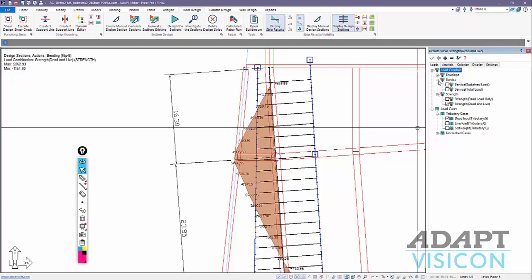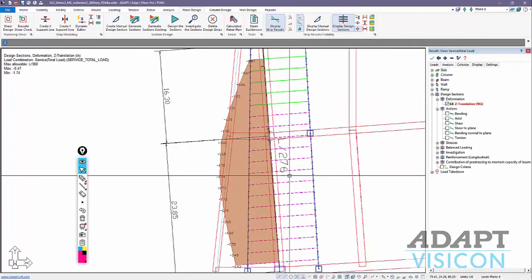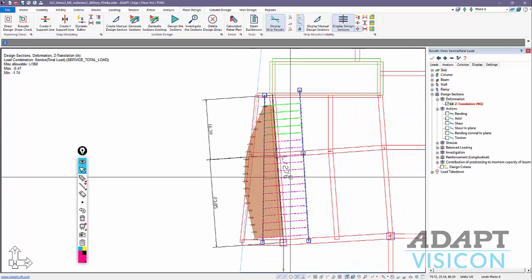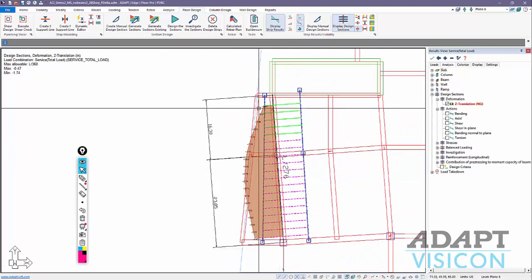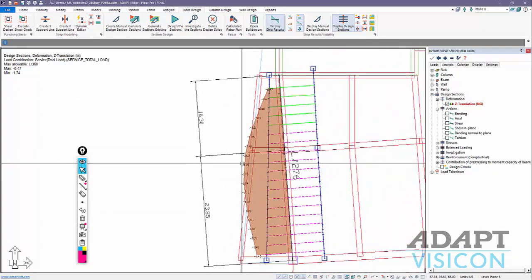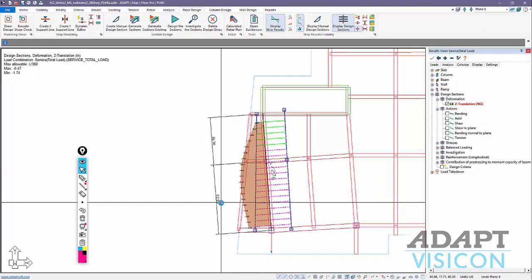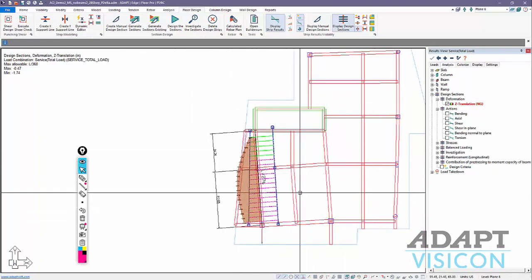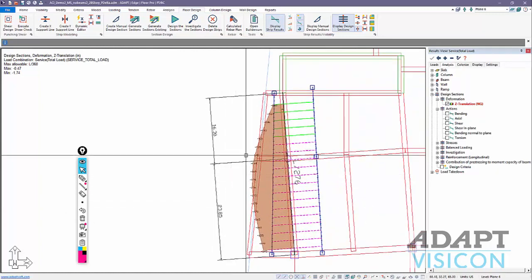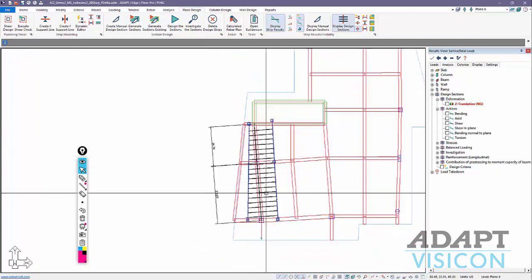If we go to a service combination, service total, we might want to check the deflection along the beam. So the deflection is L over 276 for this full span, and these are just integrated deflection values over the design cuts. These are not long-term nor cracked deflections. We would likely want to run this entire floor for cracking, and that's illustrated in a different tutorial video that we have. So again, we're just defining the different workflows here. Okay, so that's workflow 1.